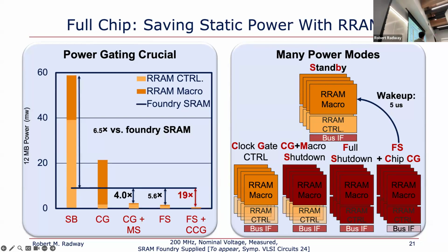Yeah, especially for some of these newer ones. For the SRAM, it's perfect. Your SRAM model is almost always going to agree with your chip if you know the right corner for the chip. The RRAM model was relatively new because at the time we got this, the memory was still not commercially released. But the trend was the correct trend.